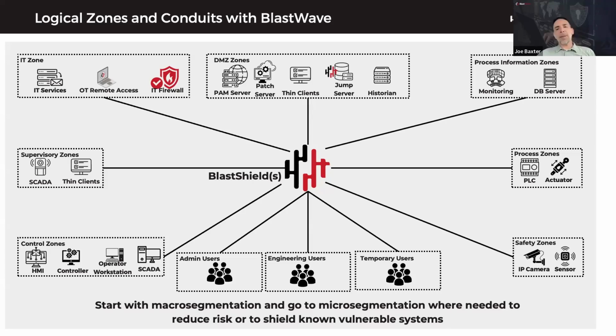I can do that. And I can make these discrete rules so that instead of having to route traffic by firewall rule to firewall rule to firewall rule, I say, I want this IP camera to talk to this server. I want this controller to talk to this SCADA server. I want this historian to get data from these two SCADA servers or these two HMIs. It's much more simple. Cam, what do you think?